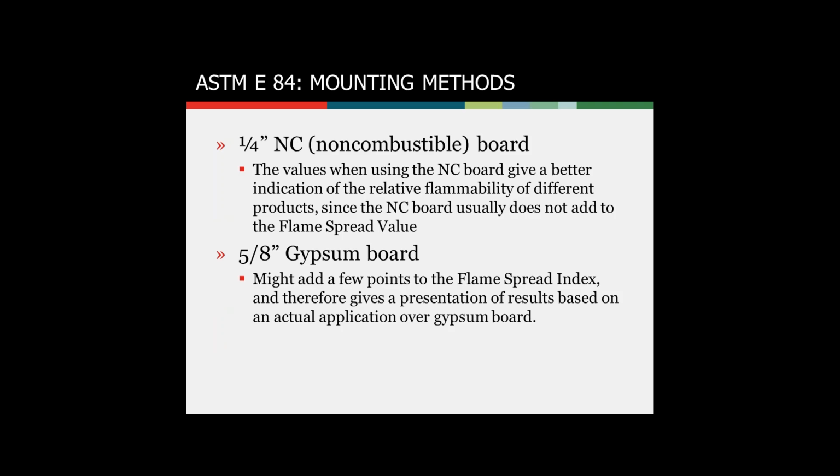This is just a description for interior finished products. If you bond the material to a non-combustible board, you'll probably get a rating that might be 5 to 10 points better than if you bonded the material to a 5/8" gypsum board. It, again, depends on the actual building application.